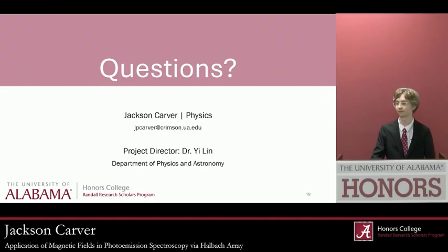I want to come back to the orientation question. So before you did that experiment, did you have any intuition about that? And can you explain why there was really no effect? I think my intuition personally, I expected that there might be subtle differences. I was taken aback by the fact that there was almost no difference in any of the 4 profiles. But I think it really speaks to the fundamental symmetry that so long as you've got each magnet rotated 90 degrees clockwise or counterclockwise as you move along the array, the same cancellation on the weak side and the same magnification on the strong side will occur. So it creates the same effect regardless.